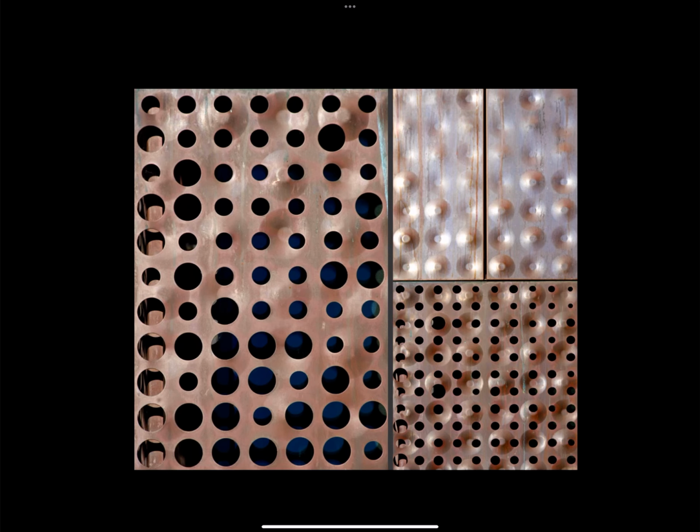So where there's a solid wall behind, it's a rain screen system, and where there's glazing behind, it's a shading system. And the strategy here is that there are circles of 5 different diameters punched out of the copper, and that the copper is also dimpled, both dimpled in and dimpled out. These two systems are both set out on their own grids, and the grids do not coincide, and they are superimposed over each other.